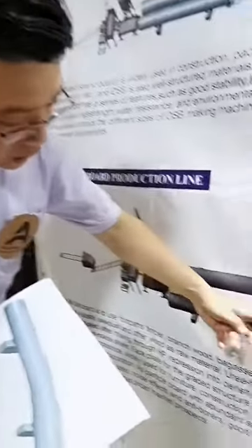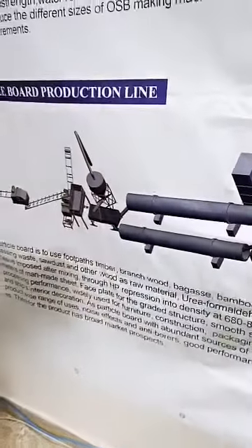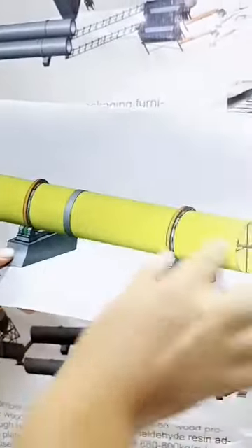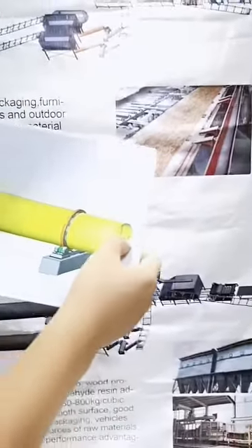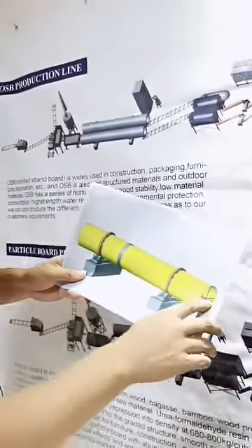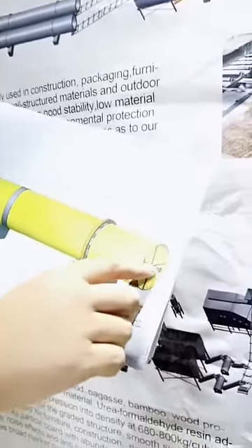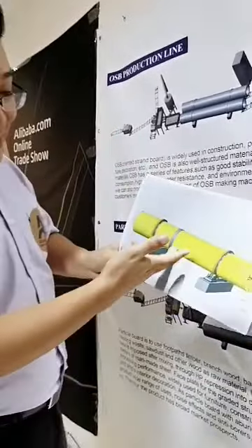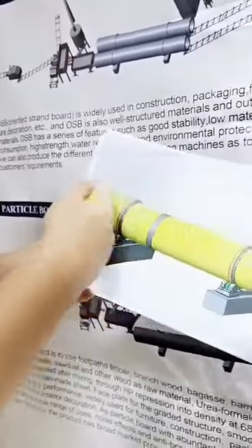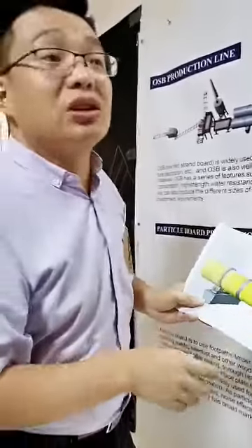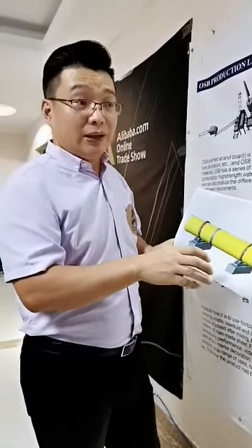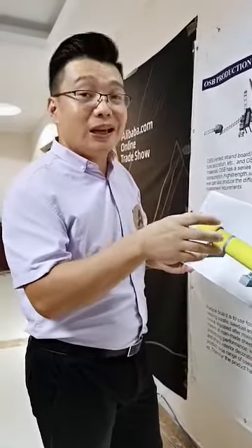The second type is made with a boiler. It's heating around here, or inside. There are many kinds of tubes, and these tubes circle here. So it's drying with a boiler. The heating oil will connect here. You can see the tube connects to the boiler, and then the boiler supplies the hot heated oil, which runs inside the tube. So it uses high temperature to dry all the materials. The second type is safer, and it has a bigger capacity.